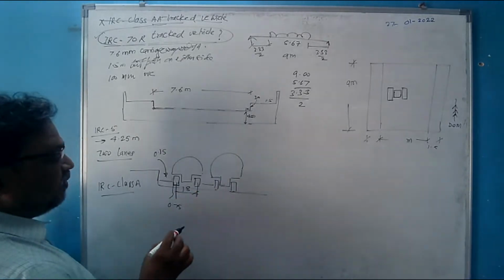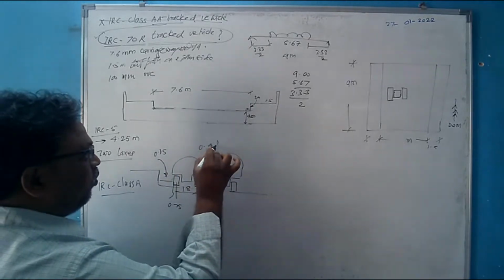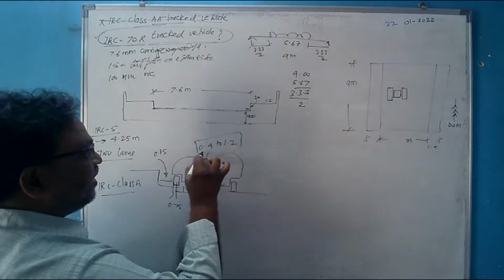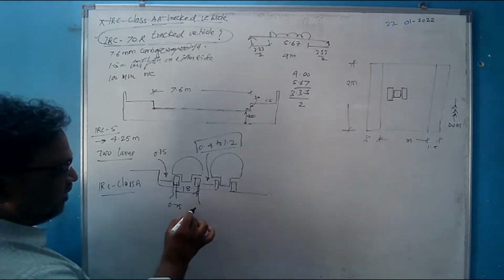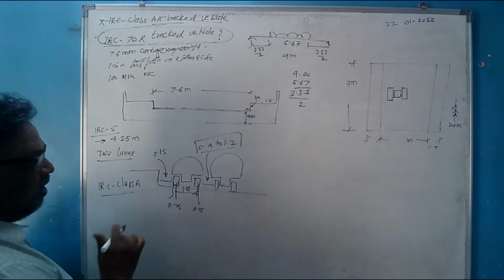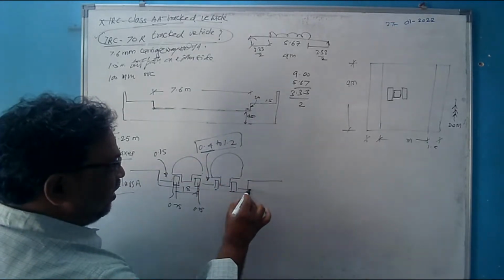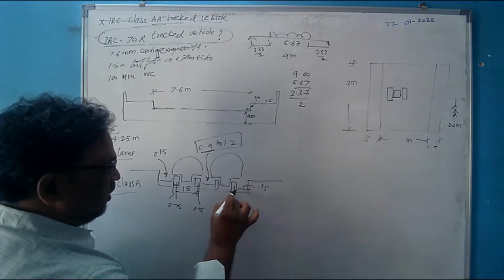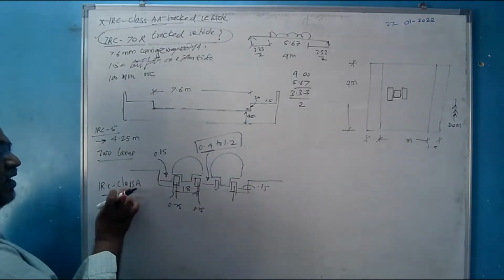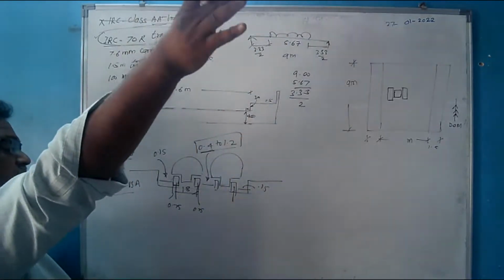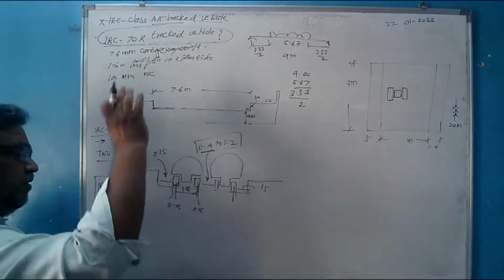This outer to outer of the wheel, again there are different guidelines available. It should be 0.4 to 1.2 meters minimum up to here. 0.4 to 1.2 from outer to outer. So for this wheel, its width will be 0.25, half of 500. If I consider 0.4 also, here again I am considering the footpath and this minimum clearance is 0.15, half of this width, because the maximum width of the wheel for an IRC Class A vehicle will be 500. We will discuss the things in detail when we discuss IRC Class A loading. When we design the bridge, we will discuss all these things in detail.